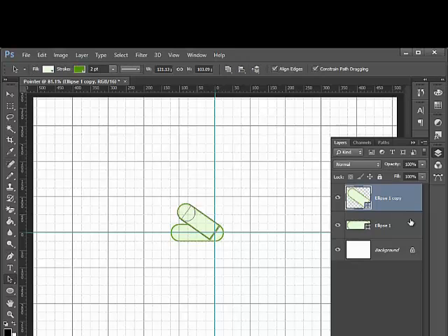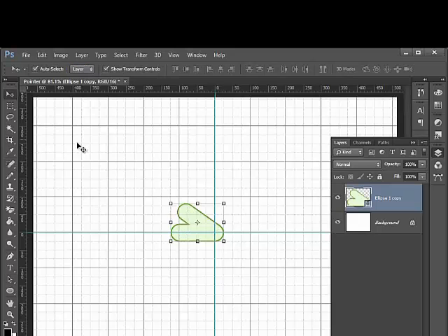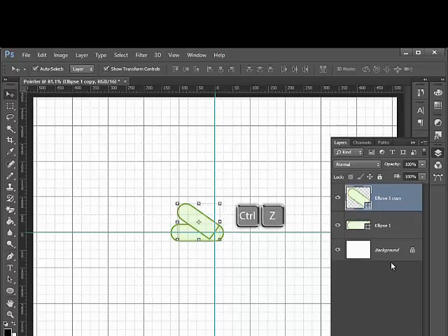We can get a better overall view by merging the stem and blade shapes together. Select the Move tool. That's about right, but the blade is a bit too long. We need to shorten it a little. To do that, we have to break things apart. Type Ctrl-Z. We need to go back to before we rotated the blade, and Ctrl-Z only toggles between the last change and what is current. However, by using Ctrl-Alt-Z, we can undo through all the changes that have been recorded.